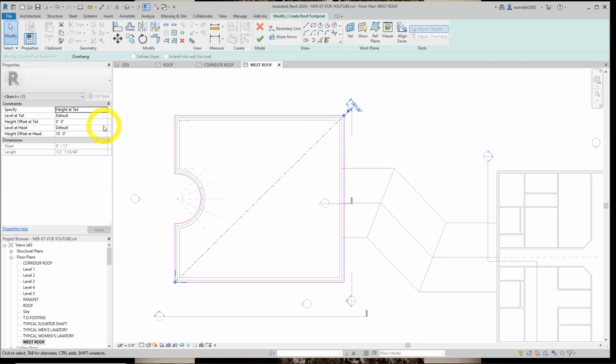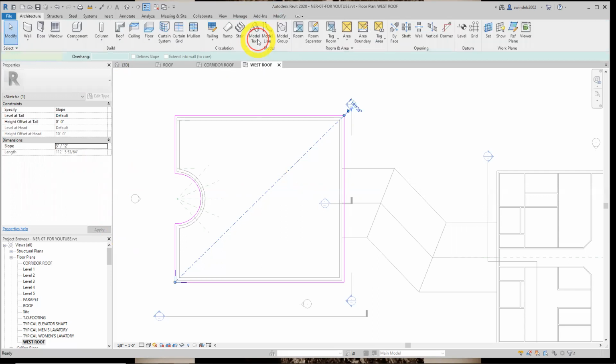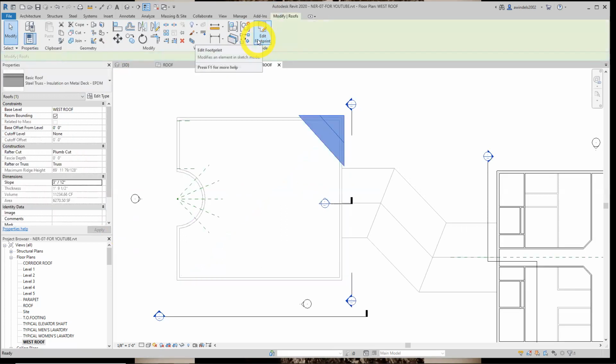Let's change a couple things in the properties in 351. Specify what it is, not exact height, but a slope. We're going to change the slope pitch to, looks like 3/12, a 3/12 pitch roof. And that's good for now. Hit finish edit mode. We'll have a range issue again, so it's going to cut off.